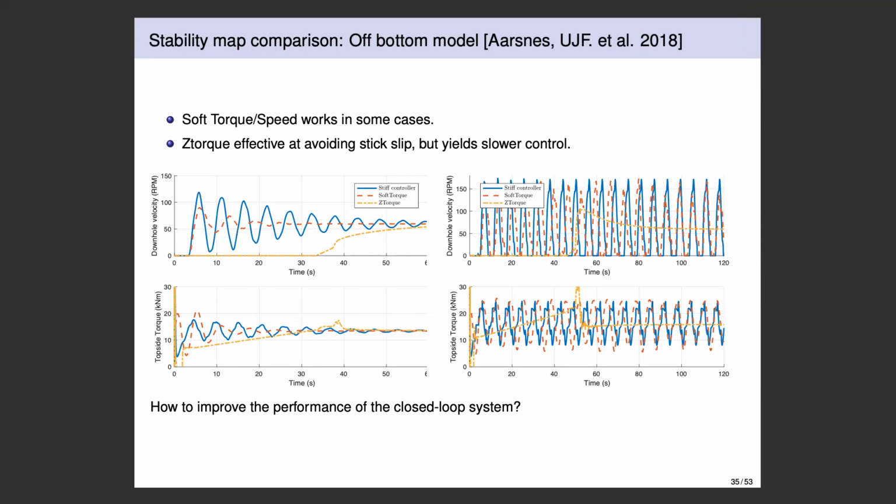And I'd like to come back to what Paul said about the friction factors as a function of depth. I was not agreeing with Paul when he said that, and then I thought, okay, maybe there are some cases where it's true. But experiments that we made with a tribometer show that what really matters for the friction factor is the fluid, the mud, not so much the type of material. That being said, there is the effect of the filter cake, which definitely depends on where you are. If you are in a porous, permeable formation, you may have a much larger filter cake.